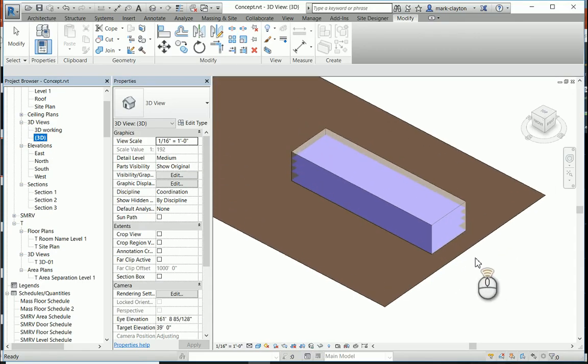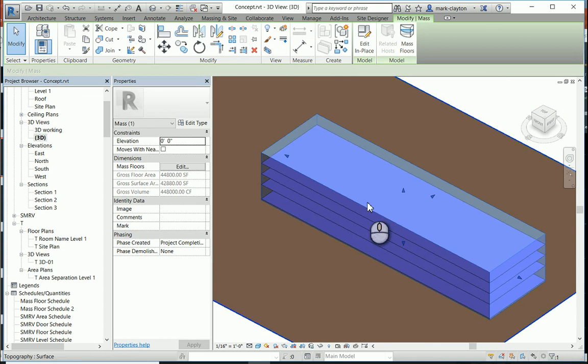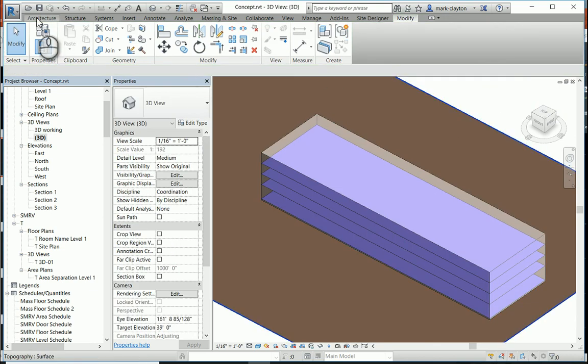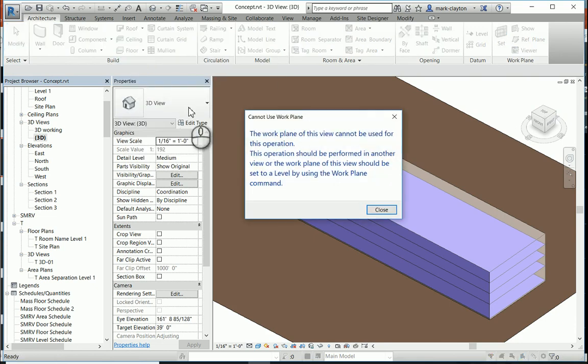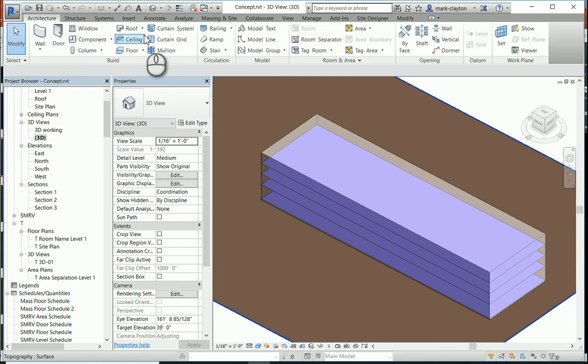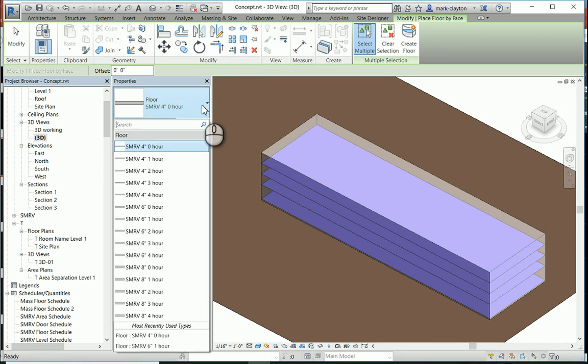So now I'm back in Revit, and I'm going to add those elements to my model. By using the wall by face and the floor by face and those tools, I can add them very quickly. So I'm going to go to floor architectural. It's not the right one. I'm going to go to floor by face, and I'm going to pick a floor.